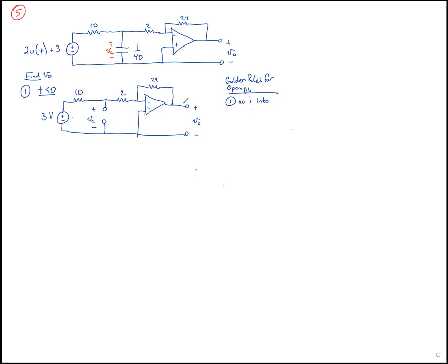What's really going on is this thing is being driven by an external source that's not being shown, and that external source is what's allowing current to flow out. But there's no current that ever goes into either the inverting or the non-inverting input. Maybe a better way to write that is to say I plus equals 0 and I minus also equals 0.